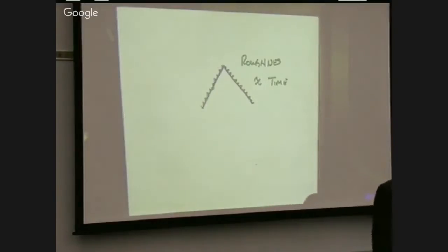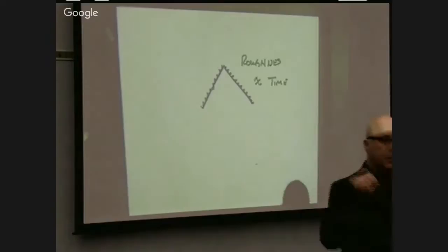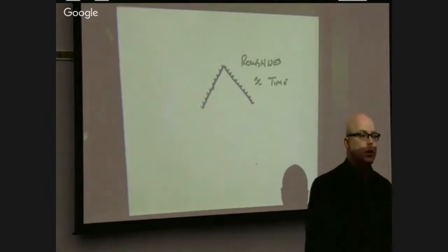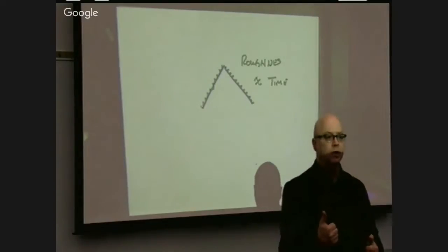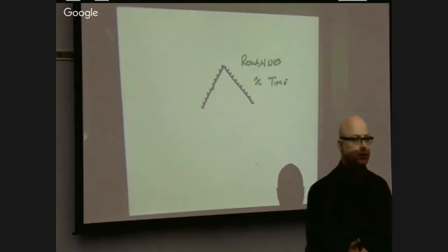If you need them to come out faster, you might need the 5-axis operation. Once you set it up once, the second part you just drop in the fixture and press go. The initial setup takes a little bit longer, but the second one just goes. So we'll consider the throughput you need, the total number of parts, and anything else we want to consider?